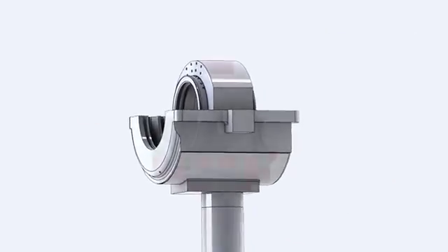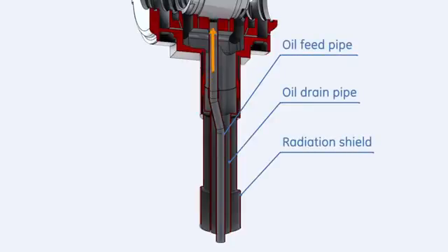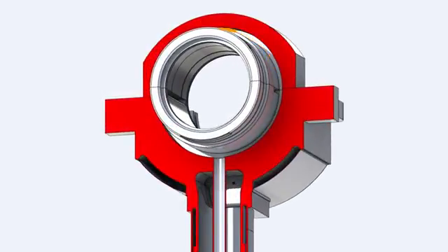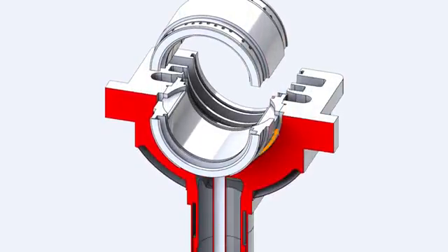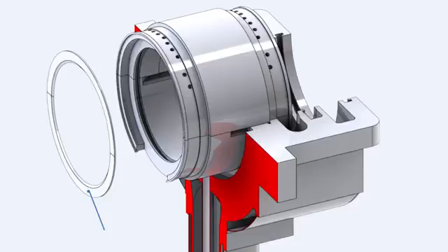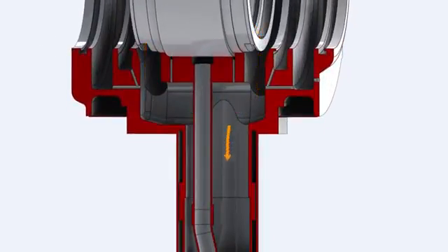For lubrication, oil is supplied through the oil feed pipe to a port in the lower bearing housing, where oil fills the annular space around the liner and is admitted inside the liner through 2 grooves machined at the horizontal matching edge. Oil deflectors are mounted on both ends of the liner to help containing oil inside the liner. Oil is drained through the vertical drain slots at the bottom of the lower liner half to the lube oil drain cavity, down to the oil drain piping.